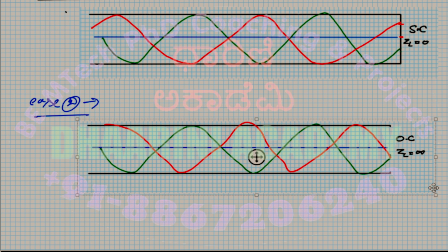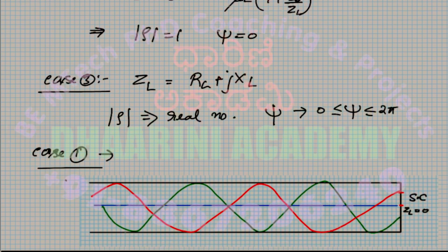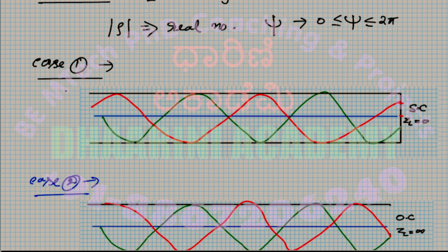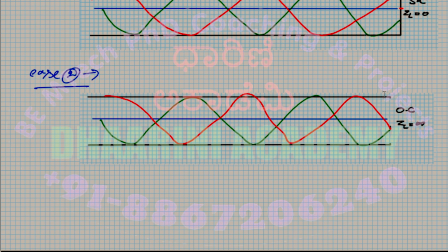it's very clear now. Let's look at the phase. What is the phase over there for case 2? Phase is equal to 0. In the sense, no change, right? Phase will never be reversed. It was going up, it will maintain its direction. So can you visualize that? If red is my incident wave, it is decreasing, and in the reflected wave also, it continues to decrease, right? So because of that, we say an open circuited line will reflect in this particular fashion.